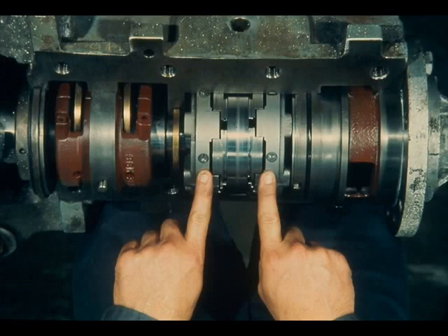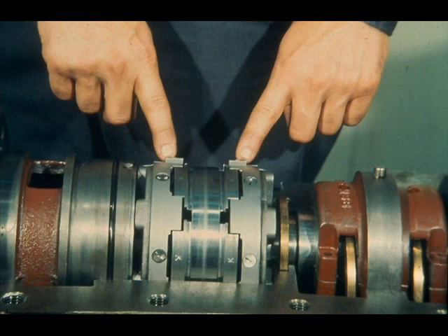The thrust collar rotates between 2 shaft bearing assemblies being pointed out here. The thrust bearings are snugly encased in the bearing housing. The thrust bearing assemblies are not permitted to rotate by virtue of these base ring keys, which are affixed to the base ring and engage a notch in the bearing housing, as is being shown here.